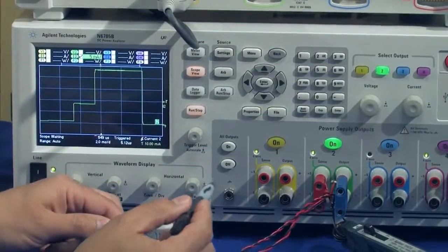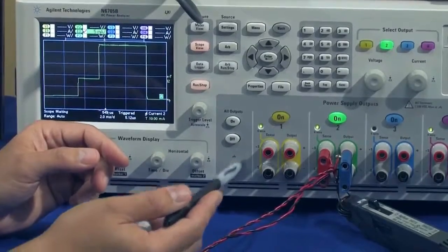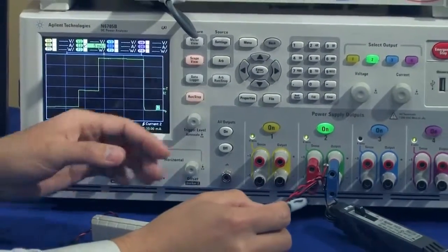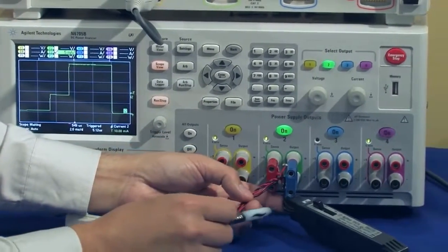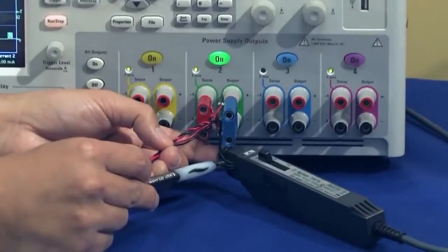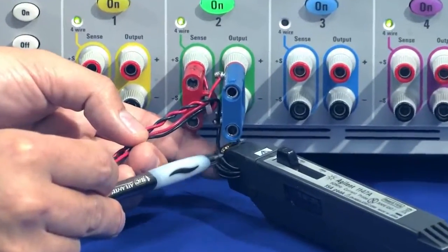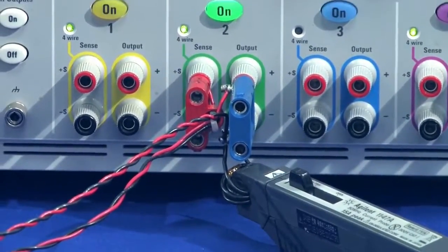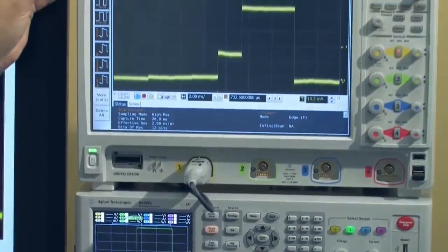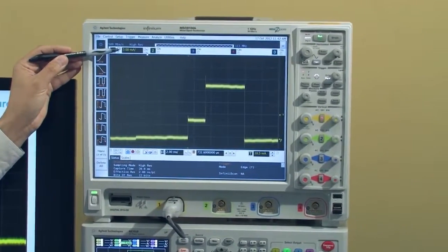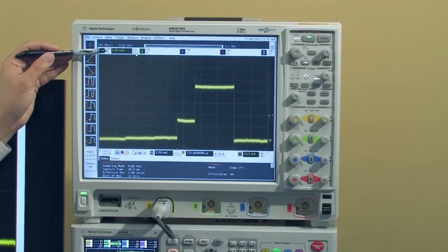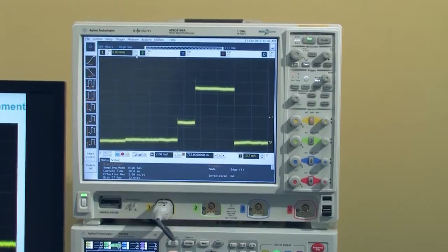But then, in order to make current measurements of this device using the traditional current measurement technique, I had to put a coil of 5 turns in order to magnify the current level during this measurement. And as you could see here, my current measurement amplitude is at 5 milliamps per division. The reason I could do this is because of the 5 turns. So I add a constant in the math of the scope and it gives me the capability of making this measurement.